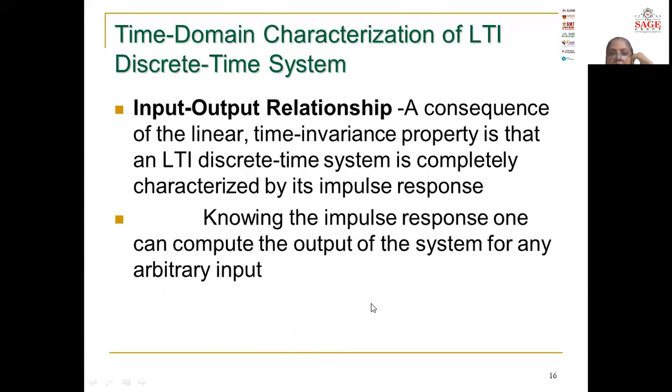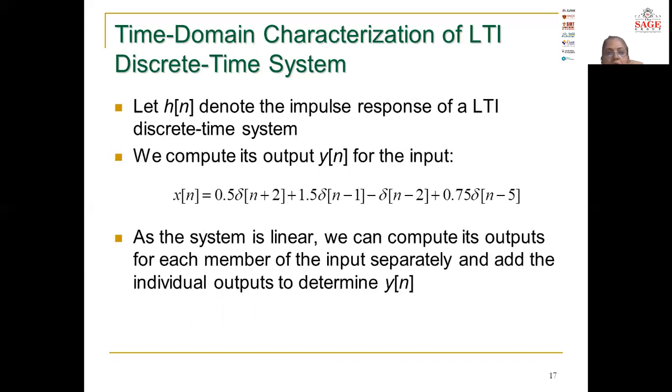Now, the time domain characterization of an LTI discrete time system. A consequence of the linear time invariance property is that an LTI discrete time system is completely characterized by its impulse response. Knowing the impulse response, one can compute the output of the system for any arbitrary input. Here we have denoted the impulse response of the system as h[n], and we have computed the output y[n] for the various inputs.